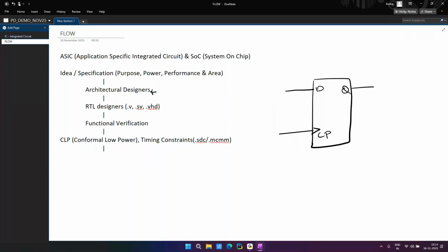That means rise edge to rise edge when you're talking about a flip-flop, edge to edge basis. When you're talking about a latch, level to level basis. During that duration my data is getting stored, and in the next cycle my data is getting released and the new data will be stored. So like that, these registers are basically storage devices also.